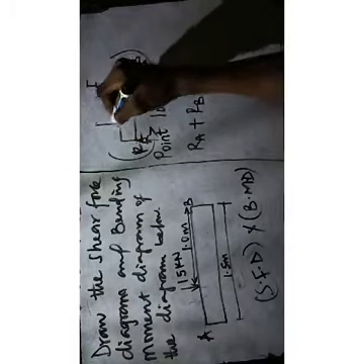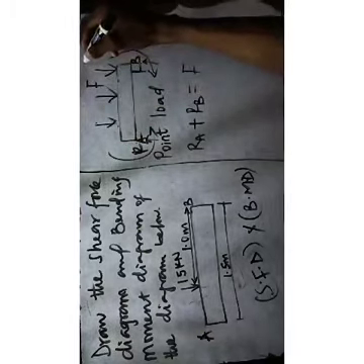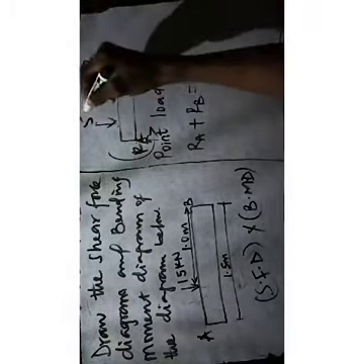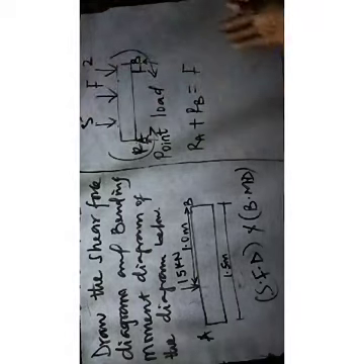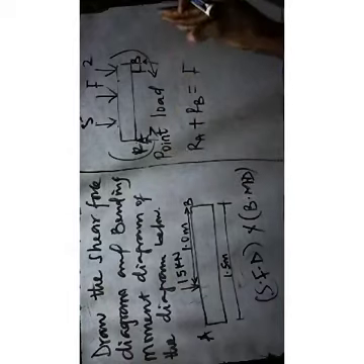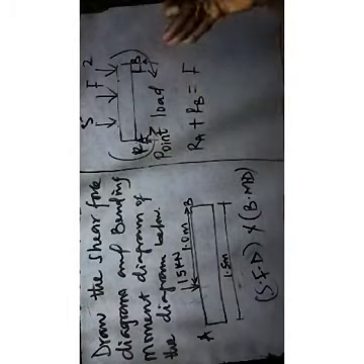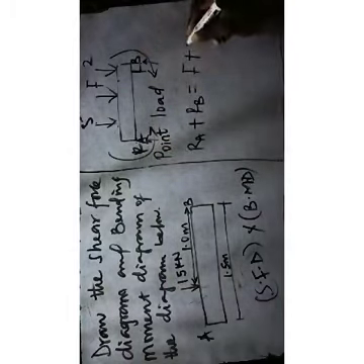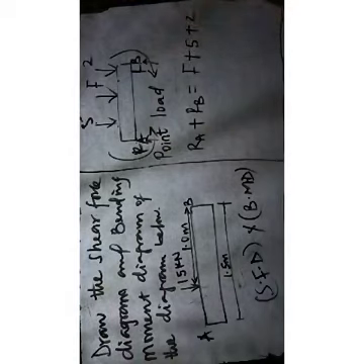Okay, let me give you an example. Let's say we have another one here, this is 2, this is 5 kilonewton. So what will be the answer? That will be RA, the reaction support at the first end and last end, RA plus RB equal to F plus 5 plus 2. Note, these are additions. Clockwise is equal to anticlockwise.